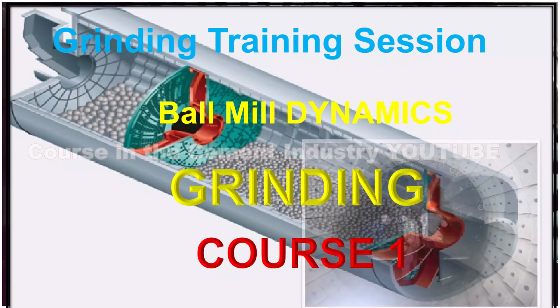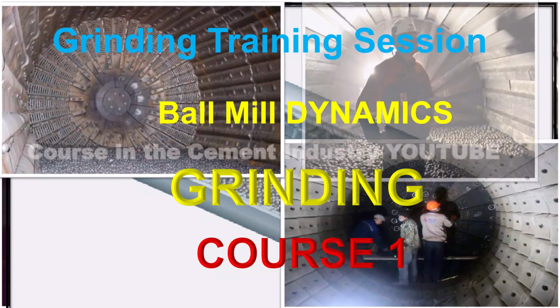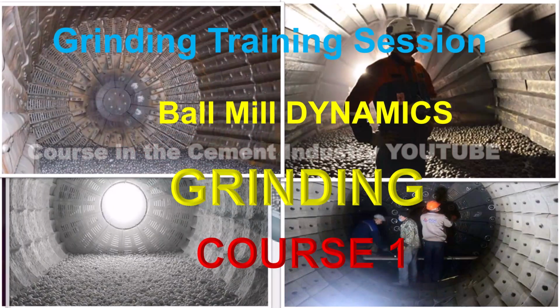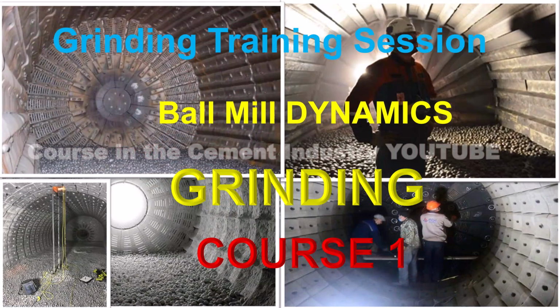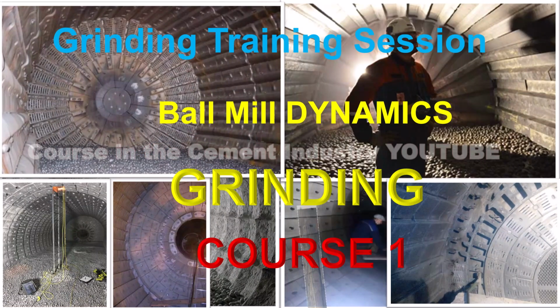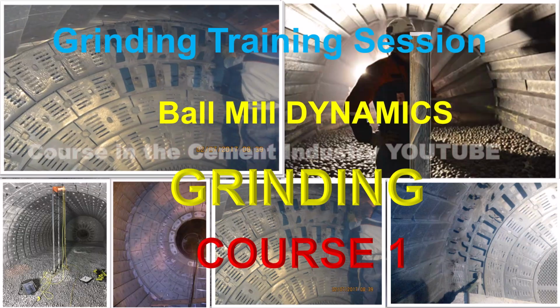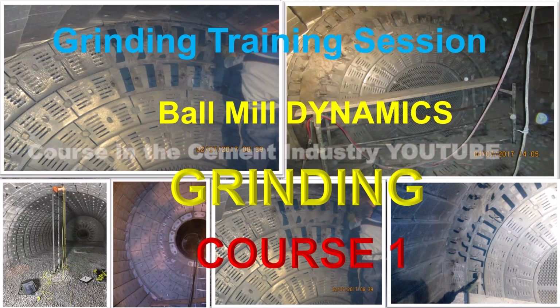The first compartment, lined with lifter plates, is for coarse grinding and therefore has a charge of large balls. The second compartment has a classifying plate lining, and a charge of smaller balls for fine grinding. Adjustable lifter scoops in the intermediate diaphragm ensure an optimum flow of material from the first compartment into the second compartment.